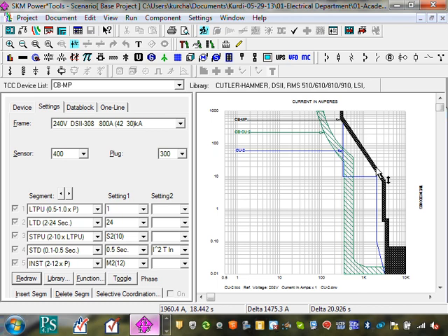And you can see the higher, here's my long time pickup, this 300 amp, and this is my short circuit right here. It's looking at right here at 3000 almost. That's going to pick up at 3200. Now I can make it shorter. Can you guys see that? Now it's going to pick up but much less than that if I bring it this way. It's picking up right now at almost 574. So that's what an adjustable circuit breaker is. Any comments, guys? Any questions?